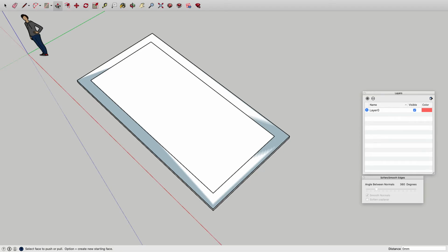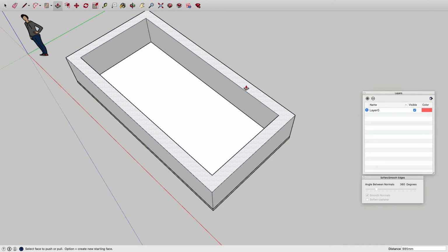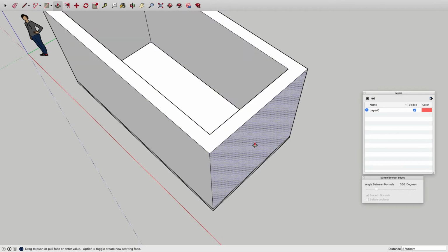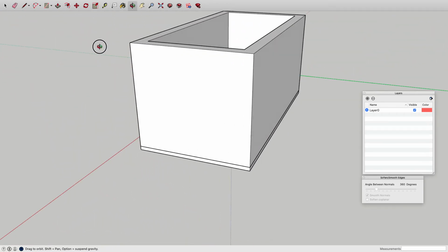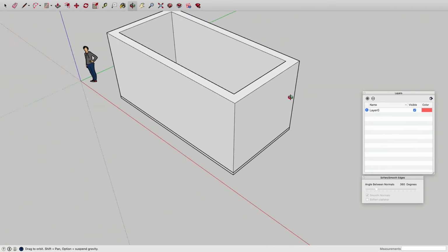I can now go to push-pull tool, and you can now rewind this and stuff, yeah? Use push-pull tool, hover over the wall, move my wall up. My typical wall height is, it's a common one for these days, not minimum height, which is 2.4 meters high. I'm going to go 2.7, so 2,700 millimeters. And that is my wall. Cool? Pretty cool. All right.